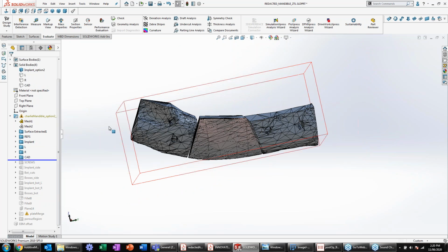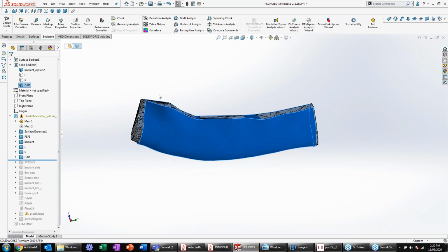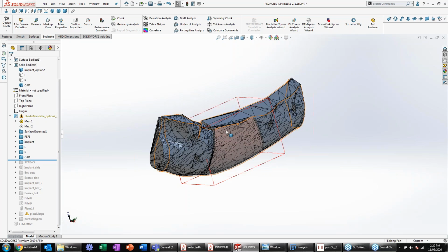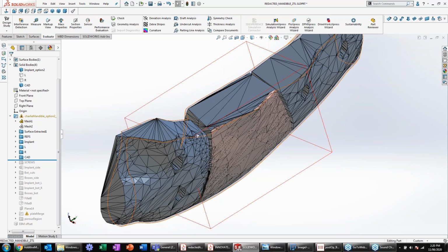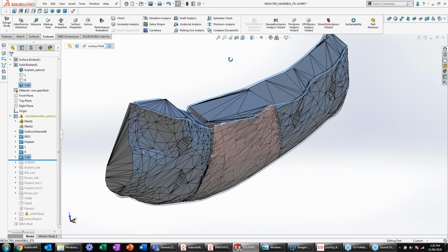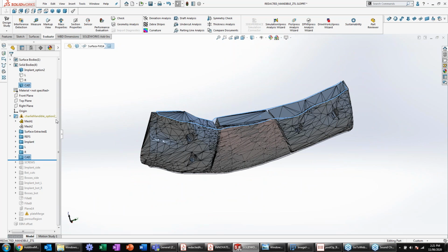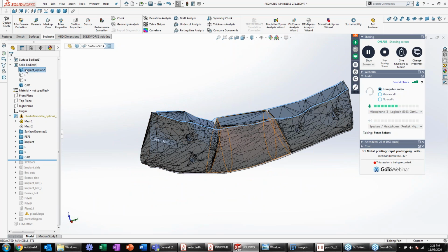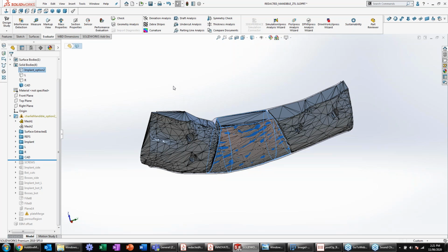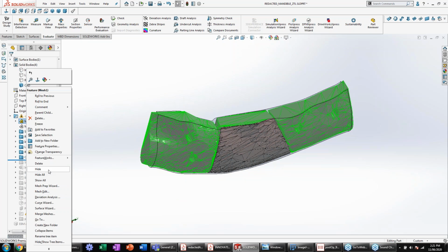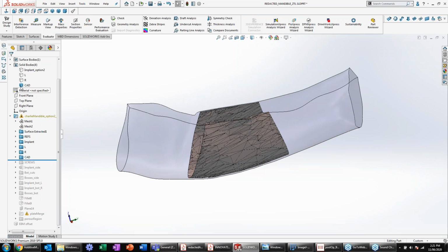What we wanted to get was a body that had an offset from where the bone was, because we wanted some clearance in it. So this center section of mesh is where we wanted the implant to be, and then we wanted to set up some references to start actually designing from. So let's hide this mesh for now. And that's kind of what we were starting with there.